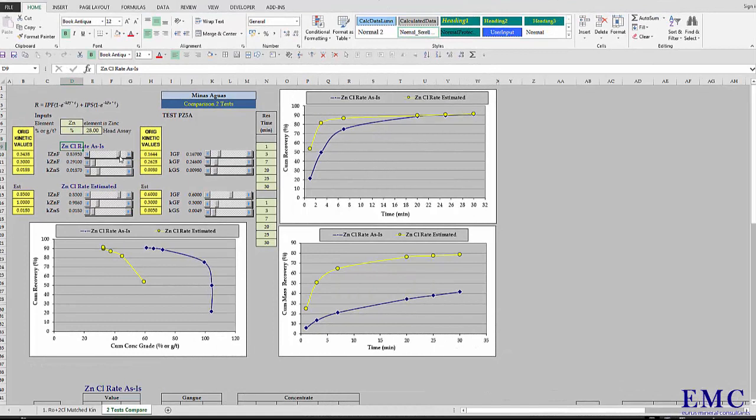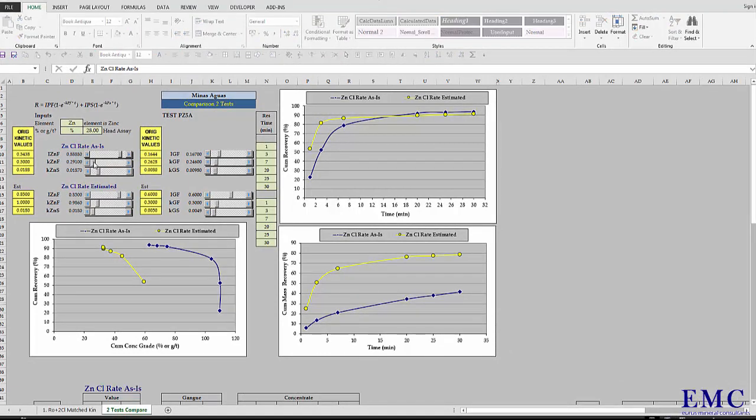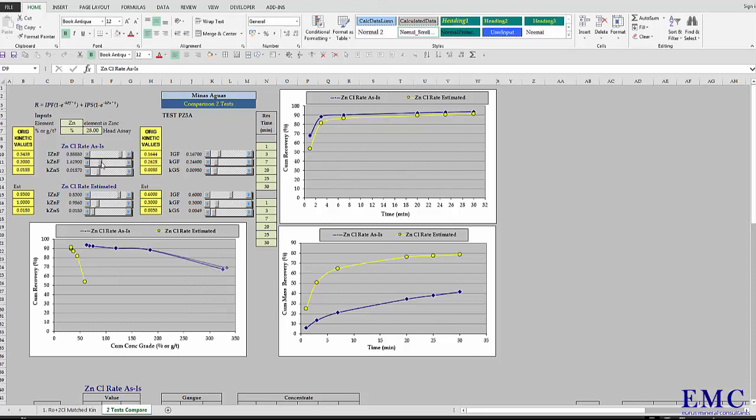So the zinc goes up to 0.88 as I put in the plant, roughly there. Fast floating rate to 1.5, and you can see what happens. This is quite a bit of fun actually when you start doing this. Let's bring that up to roughly 1.5, there we are. And the slow floating rate was 0.025. So we just use the little slider and put that up there.